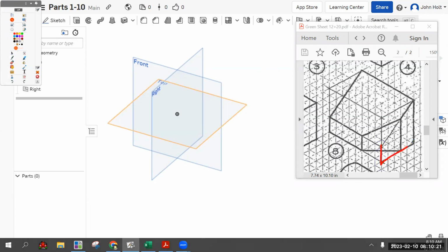We're actually going to draw the side sketch. That was a nice little shape, which looks like that, and extrude it all the way across. And then I'll show you both ways to cut away this front corner, which we'll do in a second. So the sketch on the right side is 2 tall in the front. It's 6 tall in the back and 5 wide, and then we can just connect, of course.